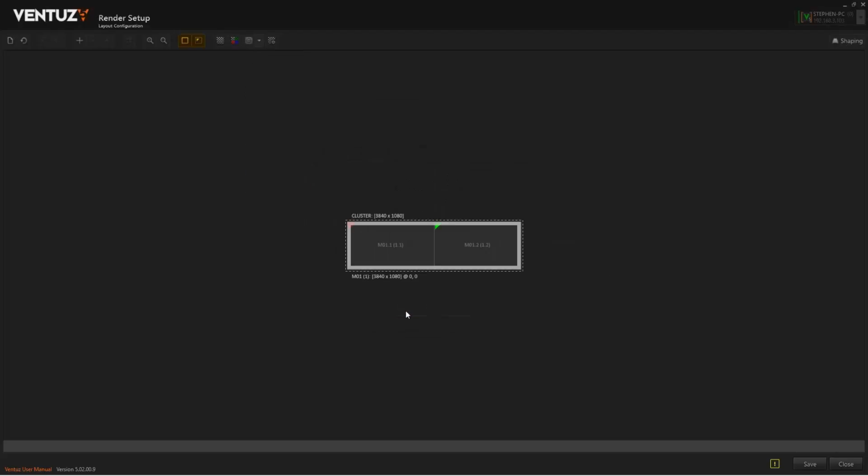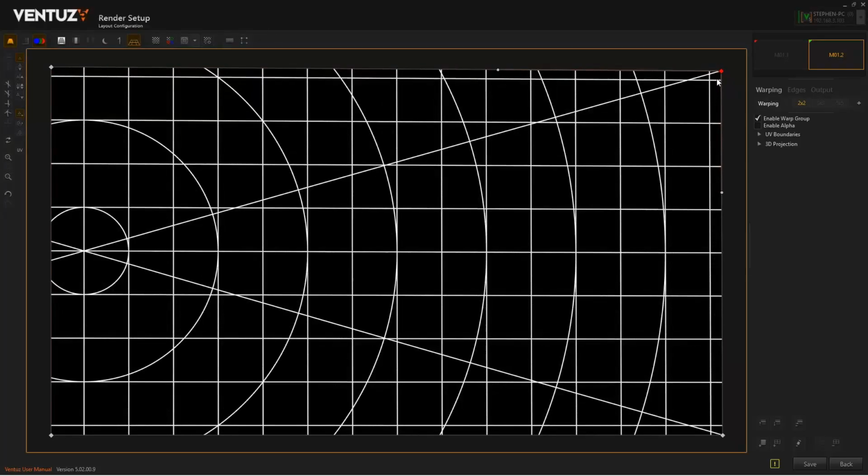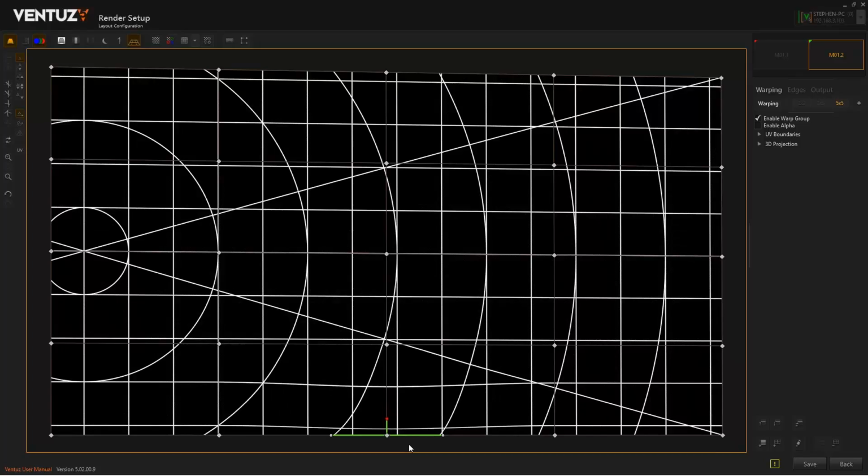So lastly, let's have a look at projection mapping, because we had talked about this in the beginning. We also have a shaping editor. Whenever you have, for example, 2 HD projectors, you would like to have them overlap a little bit to create a soft edge, and then in the shaping editor you can adjust all those settings. You can first apply them so that they fit on your projection screen, and apply keystones to them in a 2x2, 3x3 or 5x5 grid to adjust those changes to make it look correct on the specific screen.